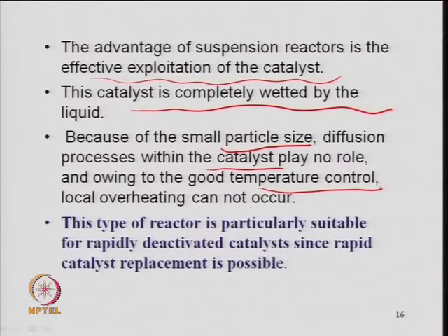This type of reactor can be used when there is rapid deactivation of the catalyst, because catalyst replacement is possible. You have a small concentration of the catalyst, and continuously you separate the gas, solid and the liquid product, and then recycle it back. So, if you have a catalyst in the system, you separate it, and if it is deactivating, regenerate it and recycle it back into the system, or change the catalyst if it is poisoned. This is the advantage in the case of a suspension reactor.